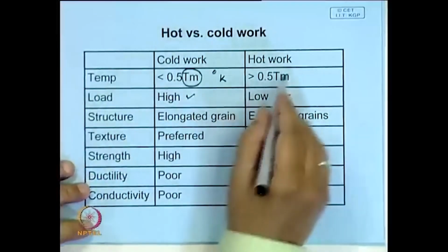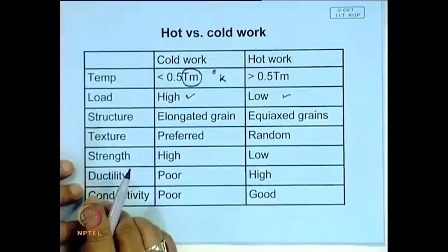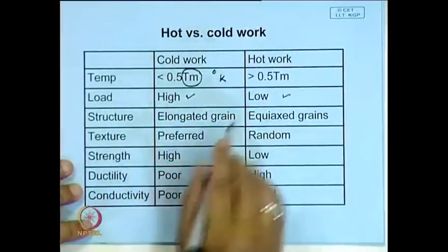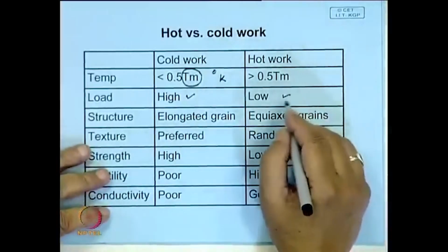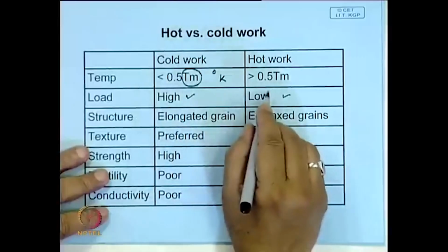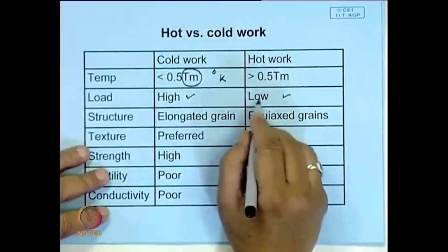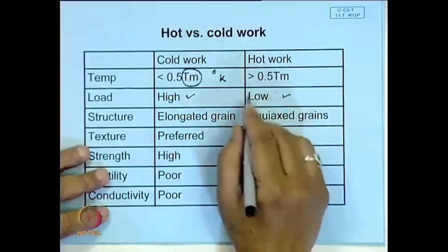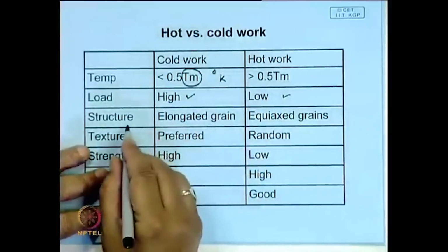But there is an advantage of cold work, because in cold work there is no interaction with the environment; it is more or less inert, whereas in hot working, depending on the material, you may have to offer some kind of protection, or else there will be scaling loss. Some of the metal will oxidize and the loss will be relatively high in hot working.